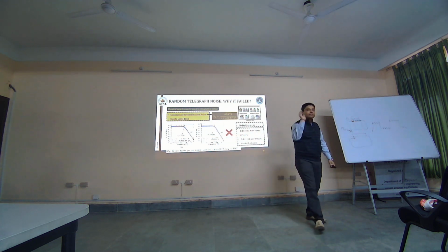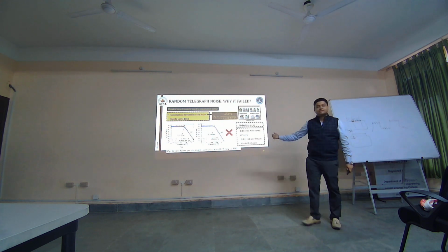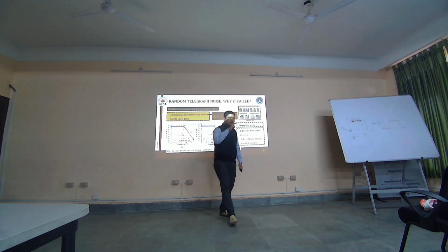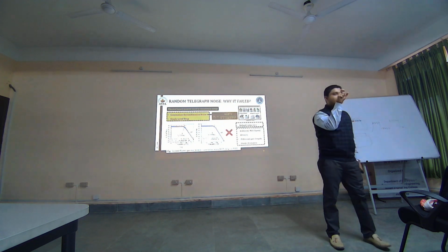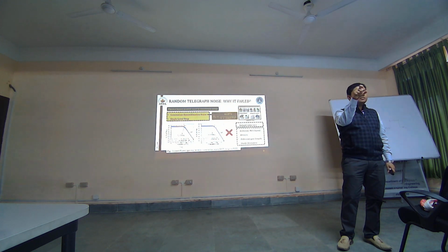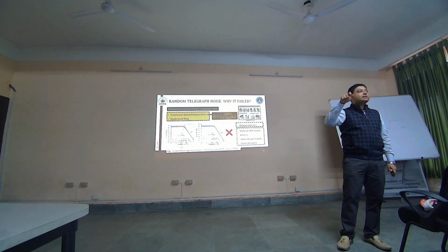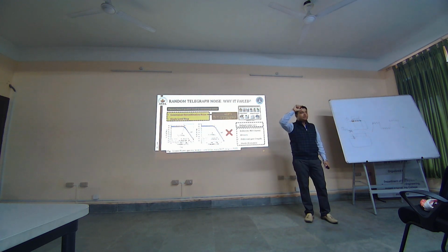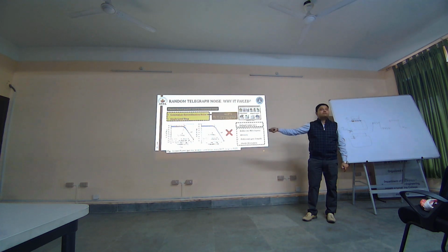So we went for the conventional tunnel FET. We also went for the NPN tunnel FET, and for both the devices, we were getting the same results. So then we again went back to the models, and we found that you have to set a definite value of the time constant, and that time constant is going to vary from one device to another. The only place of getting the time constant is if someone has done those tests experimentally, or where you have those results.